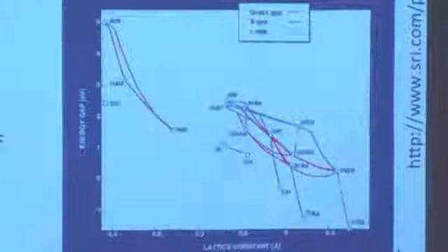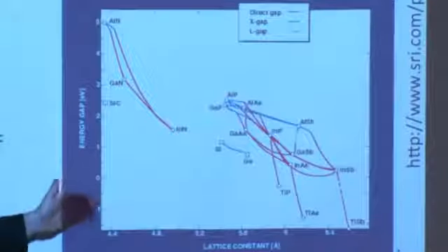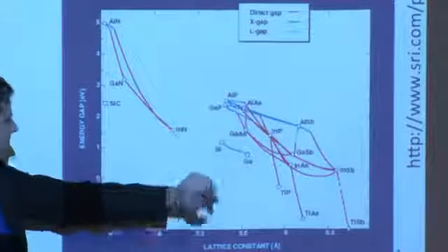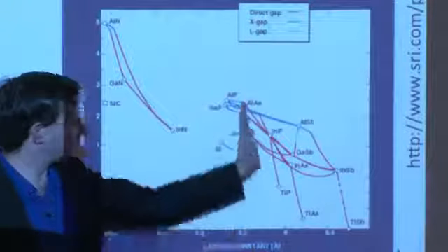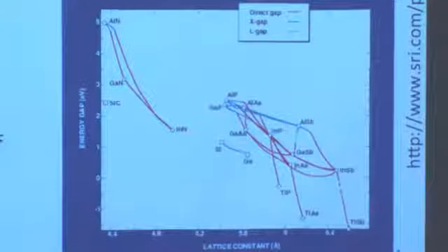And the energy gap here is important because you want maybe one material at 1 eV, one material about 1.9 eV, but you also want to make sure that they can grow on top of each other, that you're not going to get a mismatch at that interface, that the lattice constants aren't so different that you wind up with these dangling bonds at the interface where you have an atom coming down and nothing on the other side for it to bond to.